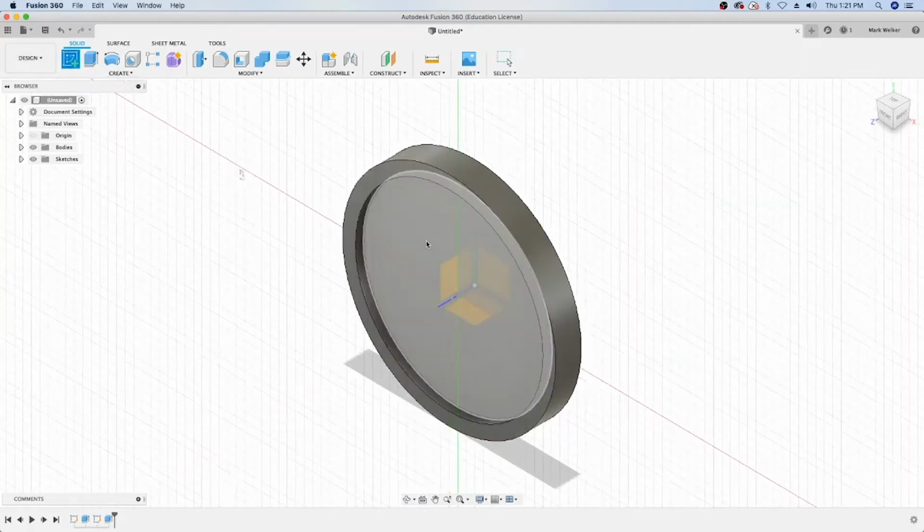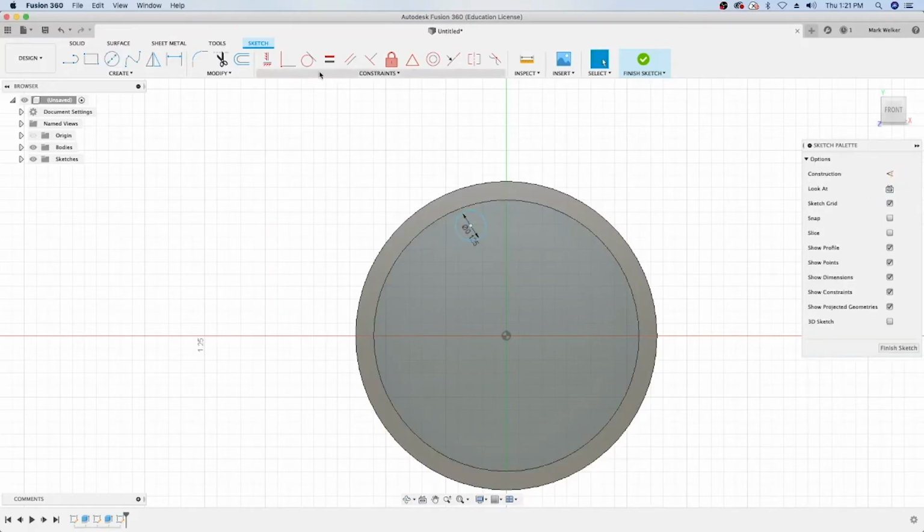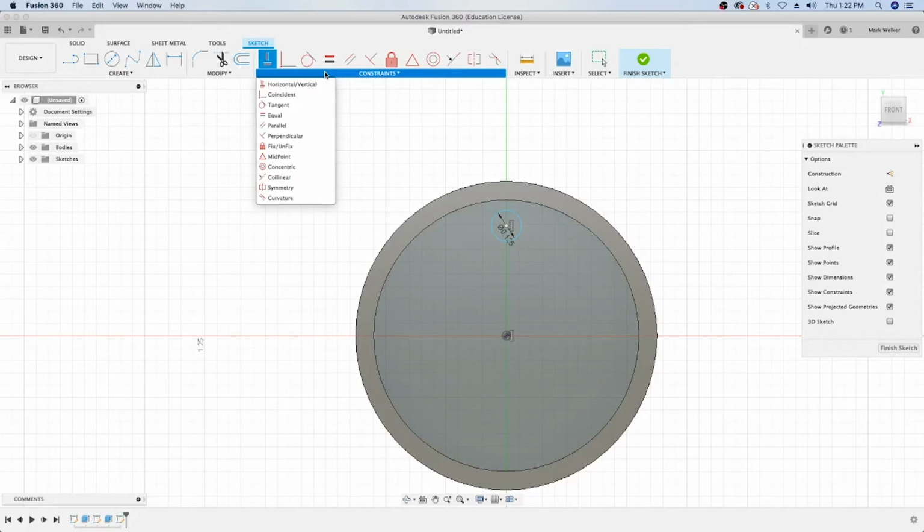Next up is where we're going to start looking at how to do the cut extrusion, and how to use some of these constraints that are a bit more prominently available within Fusion 360. So I'm actually going to create it off to the side, so we'll see how the constraints apply. In this case, the diameter of 0.125, and then we can tell it that the center point of this needs to be in line with the center point of the origin point. And then we can use the dimensioning tool, which is, let's see, I'm used to some of the shortcuts because typically I can just say that I want to put in a dimension.